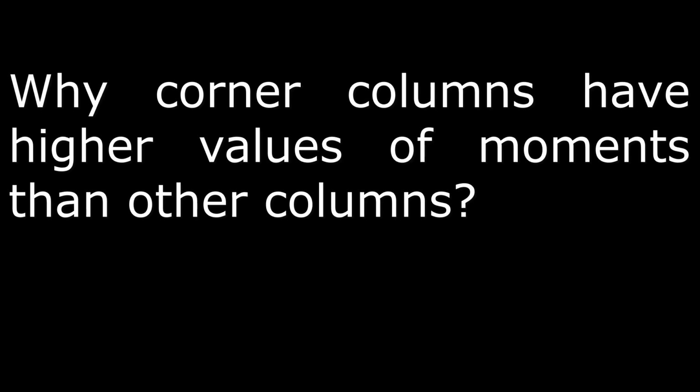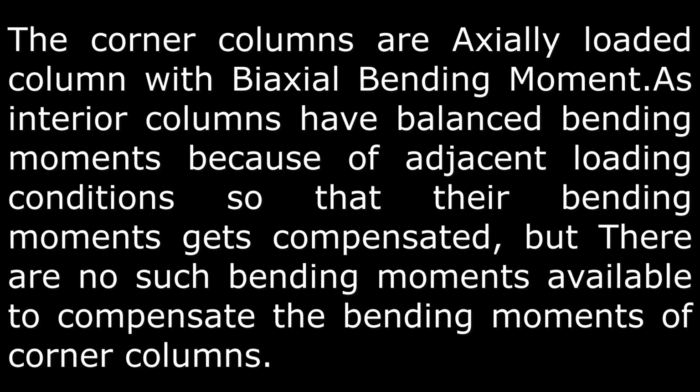Why do corner columns have higher values of moment than other columns? The corner columns are actually loaded columns with biaxial bending moment, as interior columns have balanced bending moments because of adjacent loading conditions, so that their bending moments get compensated. But there are no such bending moments available to compensate the bending moment of corner columns.